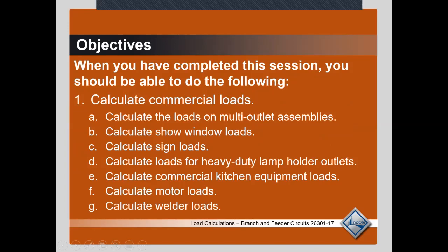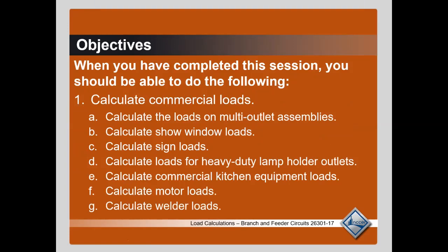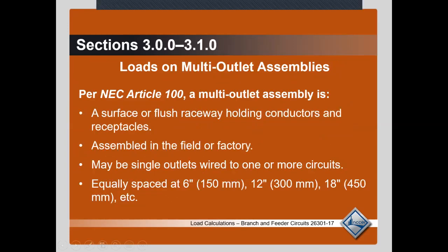Read all that. So it's saying calculate loads on multi-outlet assemblies, calculate show window loads, sign loads, loads for heavy-duty lamp holder outlets, commercial kitchen equipment loads, and motor loads and welder loads.